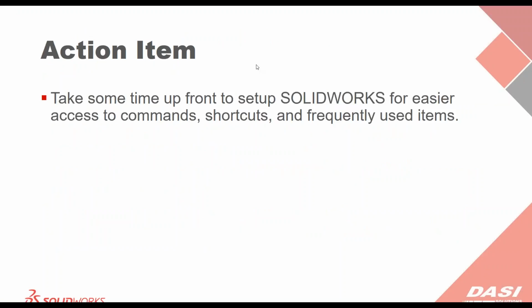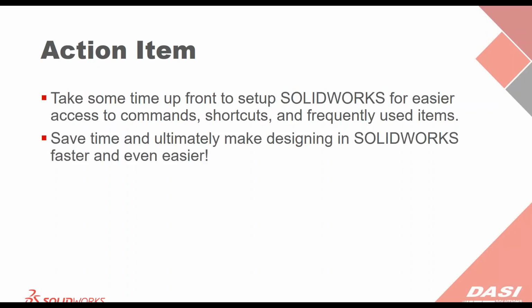All right, so let's wind this down and kind of close it out. The action item I wanted to pose to you guys out there, the users, is, take some time up front to actually set up SOLIDWORKS for easier access to your commands, your shortcuts, and your frequently used items. This is really going to save time and ultimately make designing in SOLIDWORKS faster and even easier if that's possible. But, go ahead and put in some time up front and get that set up to how you want to use it. And it will make your life a lot easier. Customize those templates off the bat, and then everyone can use them. Everyone's using the same standards, the same items, the same dimensioning schemes, and there's no differentiation between what everyone's creating.